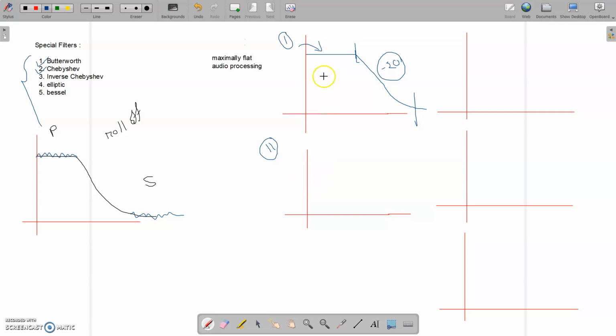The Chebyshev filter offers a much faster transition, but it has some drawbacks. The drawback is that in the first one, Butterworth, I had this flat surface in the passband, maximally flat, but in the Chebyshev I do not have flat, rather I have some ripple, but I have a much steeper slope. So I have a very fast transition in the Chebyshev filter. Understand, the ripple is in the pass band, not in the stop band region, only in the pass band region, and the transition is much faster compared to this portion. This is why we use a Chebyshev filter if we need fast transition. And another thing is that there is also an allowable range.